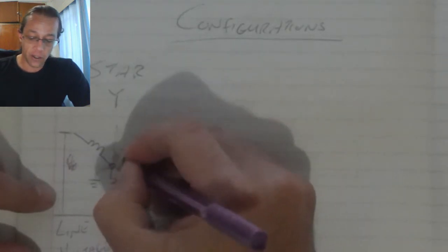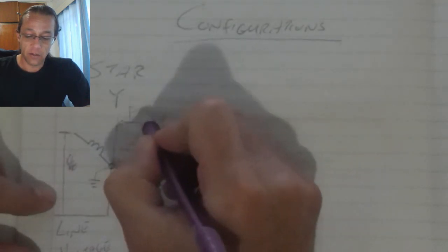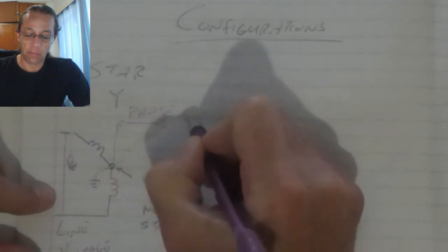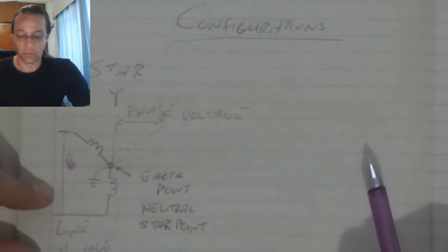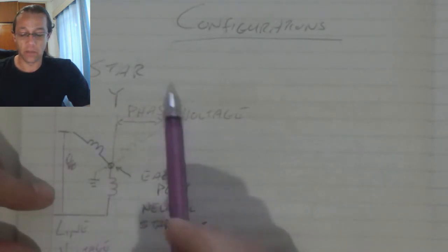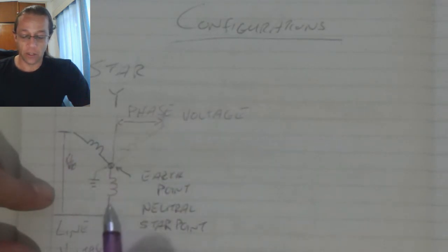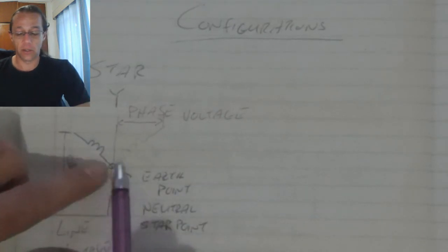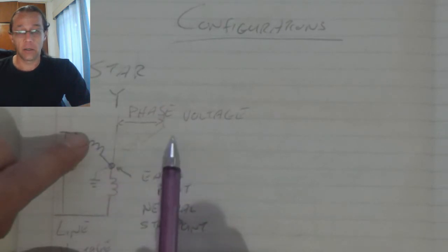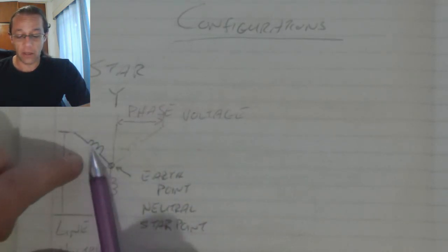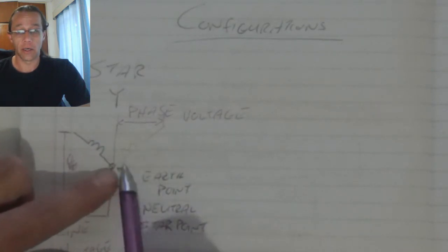If I look at a single coil, let's look at the yellow one over there, that is a phase. That is a phase value. So a line is a combination of phases. Now when we look at the system, we know that the current that flows in this coil is going to separate into the remaining coils. But later on, 120 degrees later, that current will then again be equal to the sum of those two currents.